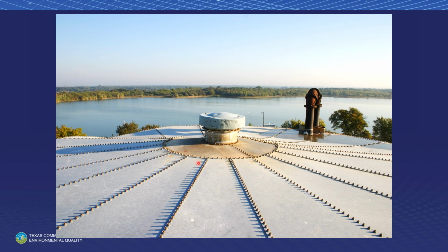And in the winter, the moisture would condense on that screen, and as soon as the service pumps turned on, no air went into that tank, and it collapsed the tank. All 3 of my tanks had gooseneck vents that scaled up due to the humidity and the 20-degree water temperature. But I'm assuming that could also happen on this tank here.